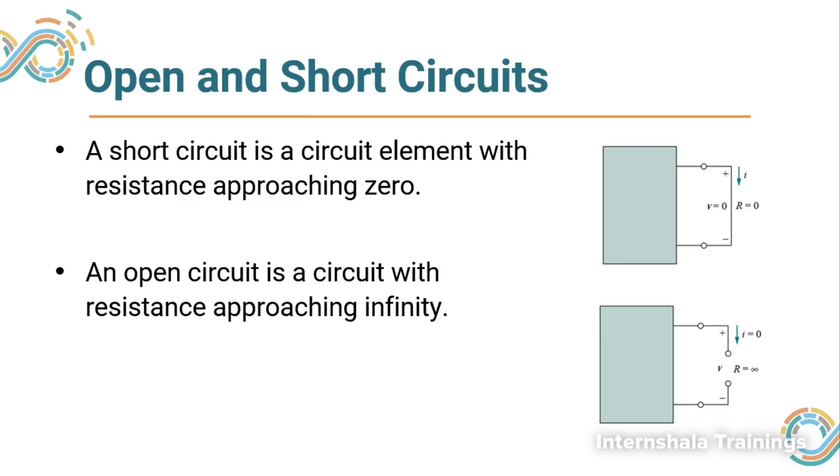The voltage at point A and B can be calculated by other circuit elements, and the relative voltage between A and B will be the difference between voltage A and voltage B. So two definite things are resistance is infinity and current is zero. Nothing can be said about voltage by looking at the open circuit alone. These concepts should be very clear in your mind.